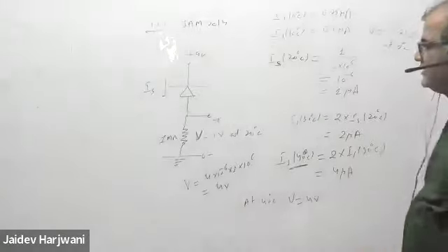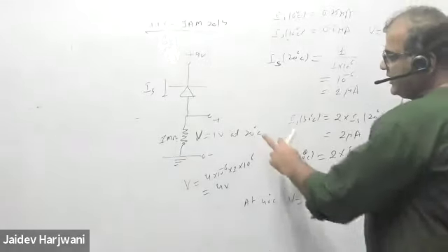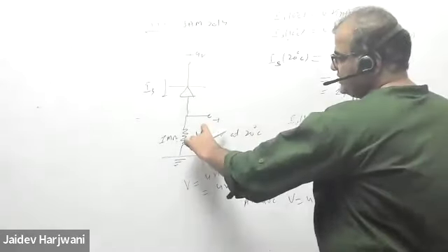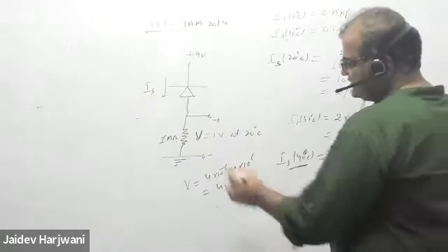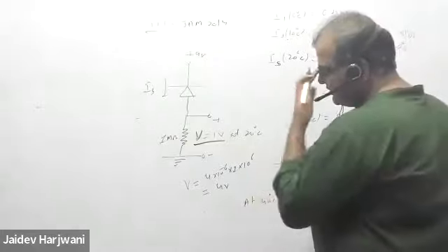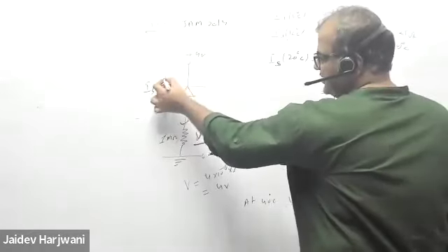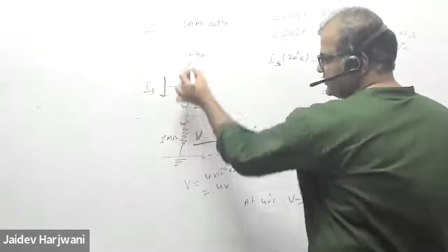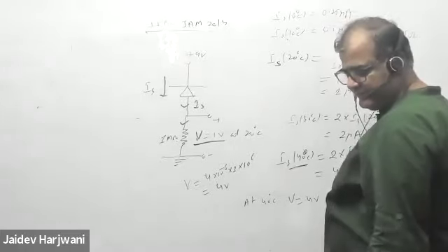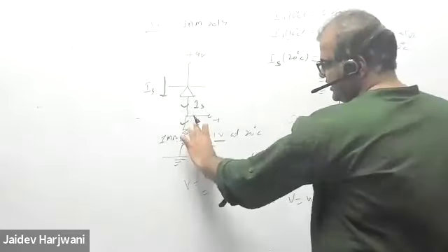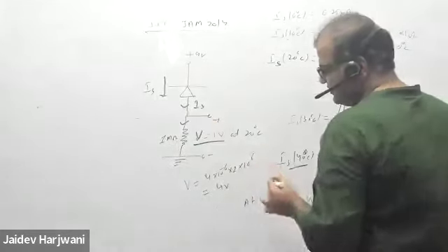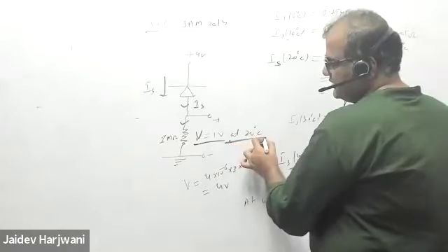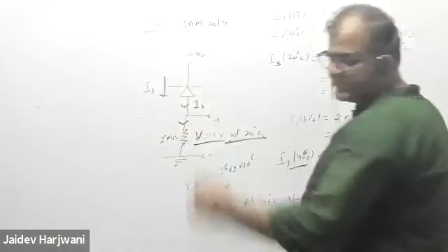In the question, it says at 20 degrees centigrade, the output voltage here is 1 volt. Obviously some current is flowing here, which is the reverse saturation current, coming from the negative to the positive plate, and this current is flowing here. So I know the voltage, I know the resistor, I can find the current. What is the current at 20 degrees centigrade? Because the current here itself is the reverse saturation current, na?